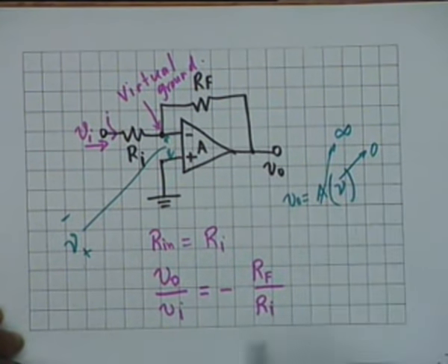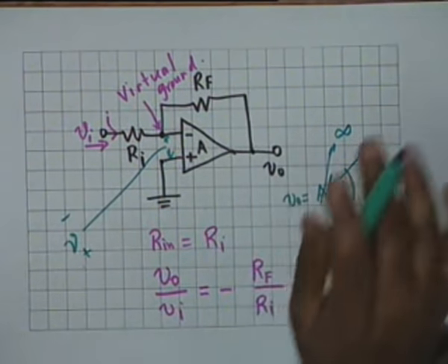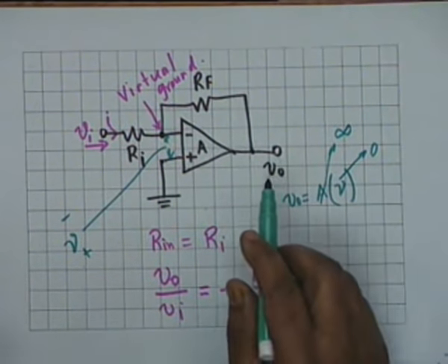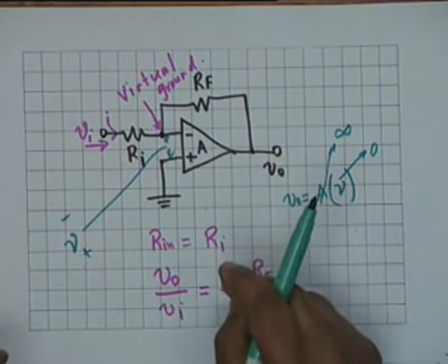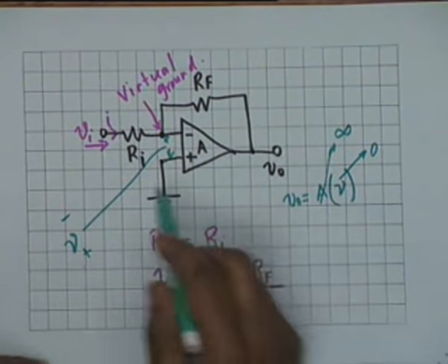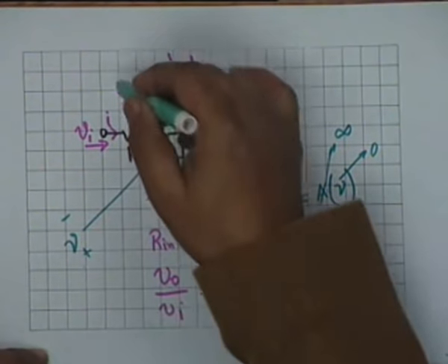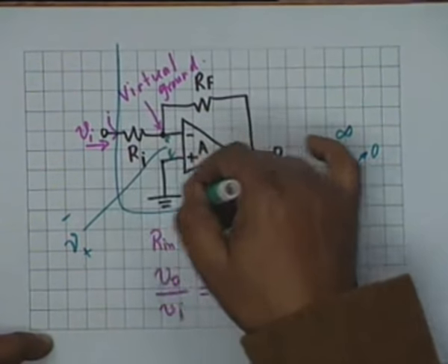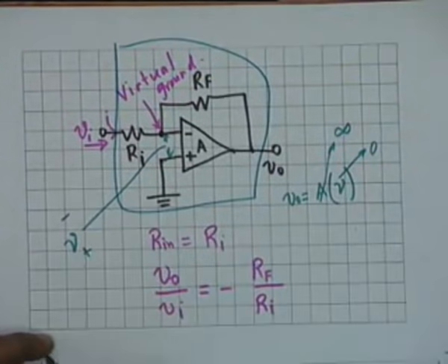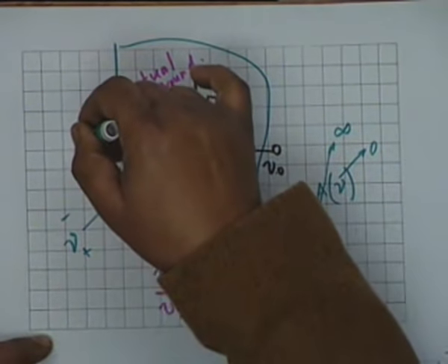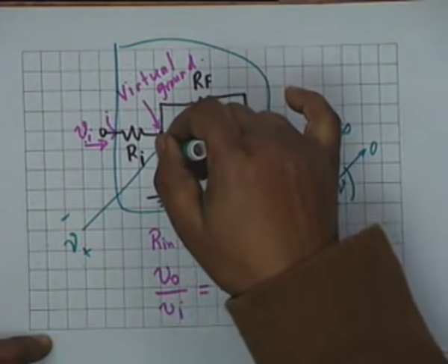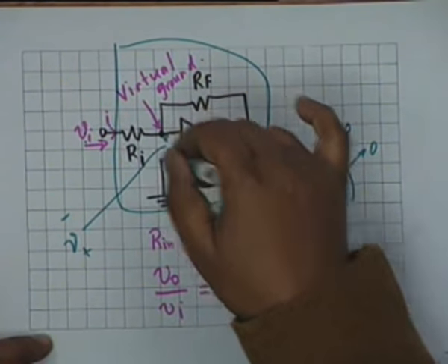This was the assumption. Now, the gain that we are now talking of is not what is applied at the inverting terminal or non-inverting terminal directly, it is applied through a resistance, and therefore the total amplifier circuit is this. It is V0 divided by this Vi, not what voltage appears here. Agreed?